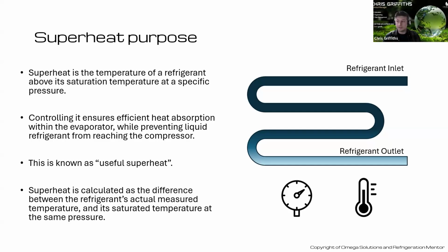With electronic expansion valves, we only have a probe, and we have a transducer, maybe, to measure the pressure, and then we need to have a controller which then converts those signals into an actual process to drive open or close our expansion valve.